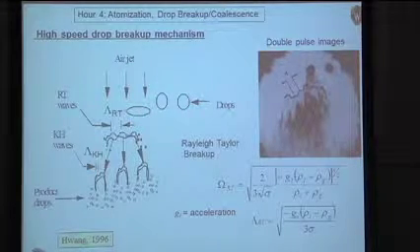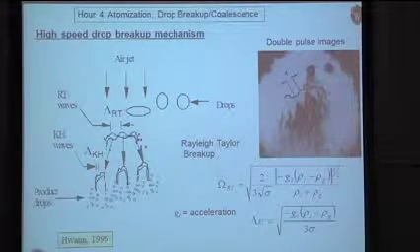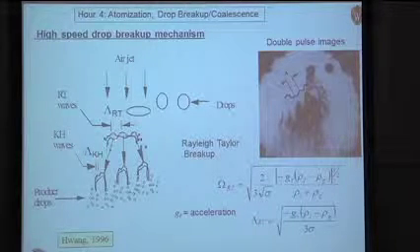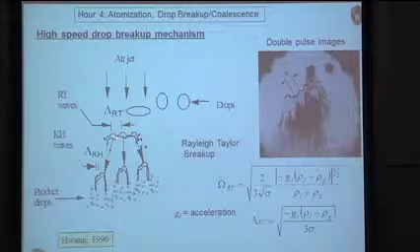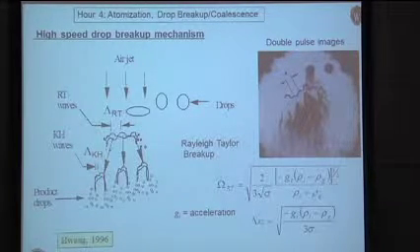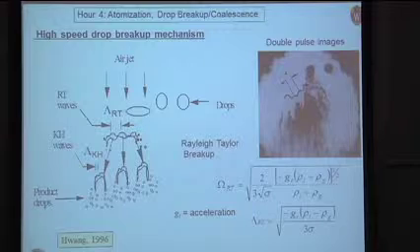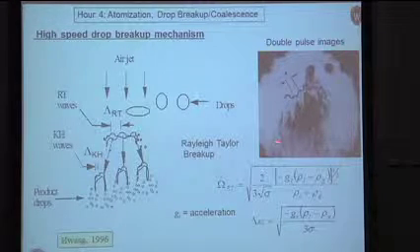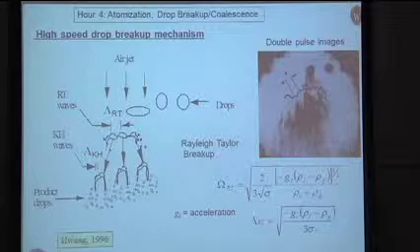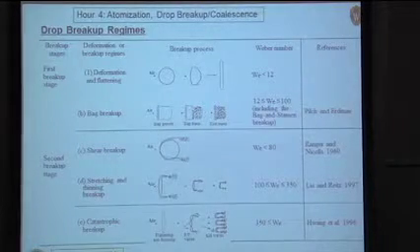They accelerate drastically. The acceleration leads to the formation of these Rayleigh-Taylor waves, which then essentially snap off pieces of the jet, which then are subject to the Kelvin-Helmholtz waves that we discussed before. And we think that this is a reasonable explanation for what you're seeing here. A combination of two breakup agencies.